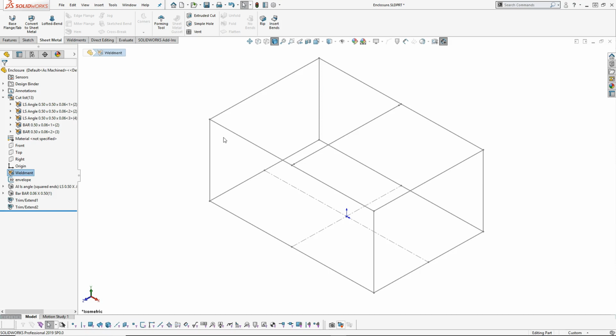to build this frame in an assembly, and then the weldments will be part of that top-down assembly. The sheet metal will be another component. So the frame gets built into the assembly, the weldment becomes a sub-part or a part component in that assembly, the sheet metal becomes a separate component in that assembly.